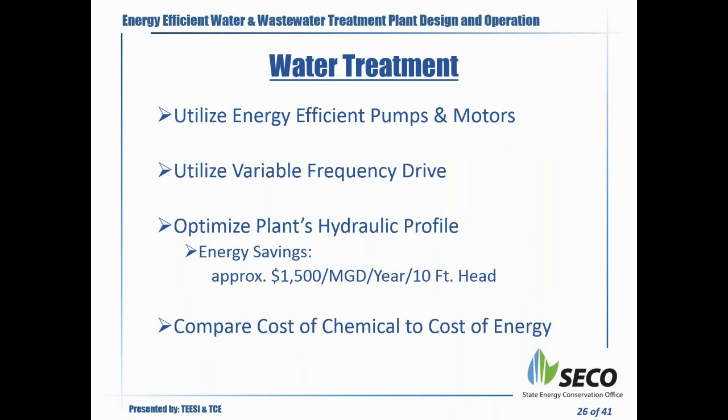When we look at your water treatment facilities, we look at whether you're utilizing the energy efficient pumps and motors, whether you're utilizing variable frequency drive units. We like to look at your plant's hydraulic profile and make sure you're only pumping your water one time and not having to have intermediate pump stations because a hydraulic profile is a bit off, or you add a unit process that needs you to pump the entire volume of water back to a unit process.